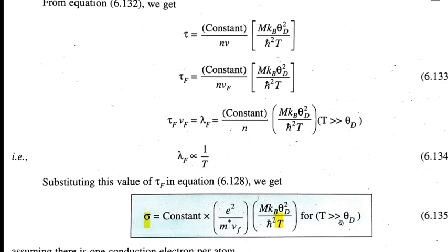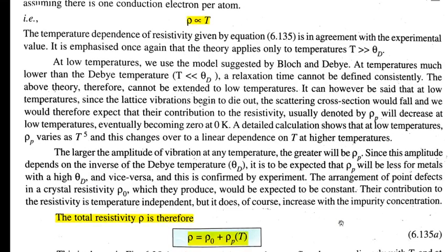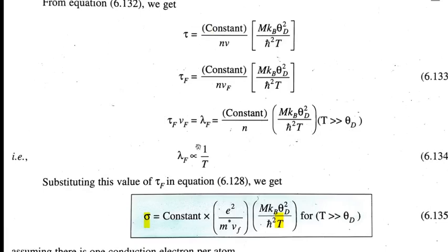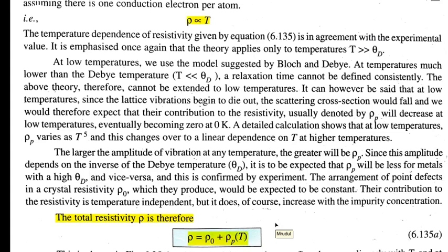In short, we are not touching the lower range of temperature, because as we had said, the electrical conductivity and its behavior are a little bit different in the lower temperature zone. Okay. So if sigma is inversely proportional to the temperature, again let me take you back there, then naturally the resistivity is proportional to the temperature, and therefore, for the total resistivity, Matthiessen's rule comes into the picture. So it is in two parts, rho 0 plus rho p as a function of T.